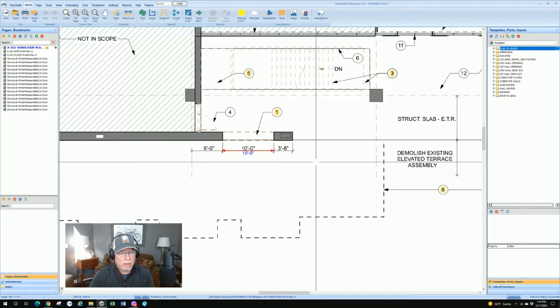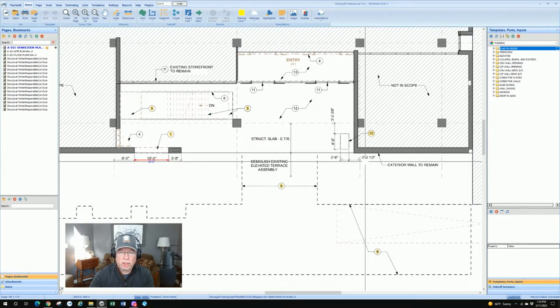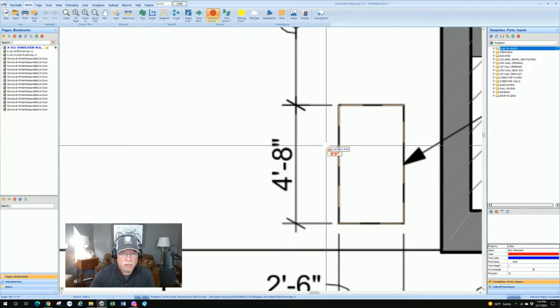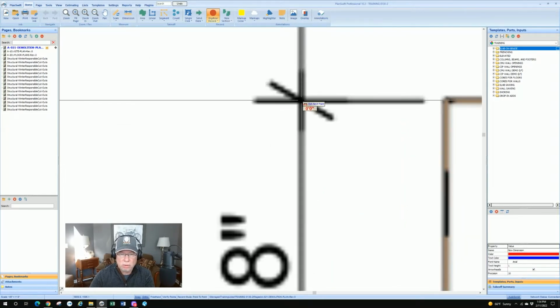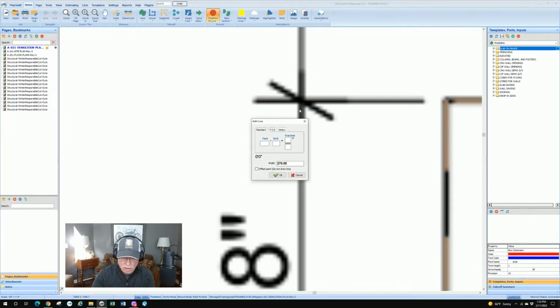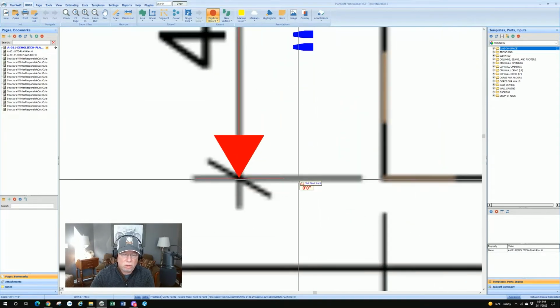If it's 1/8 in one direction, it's 1/8 in both directions. But if you really wanted to, there's nothing wrong with checking here. Here's a vertical scale. I just go in there and click on the dimension again, click on it, hit the down arrow key, and this was 4/8, so I enter 4.8. Hit enter. Good to go.